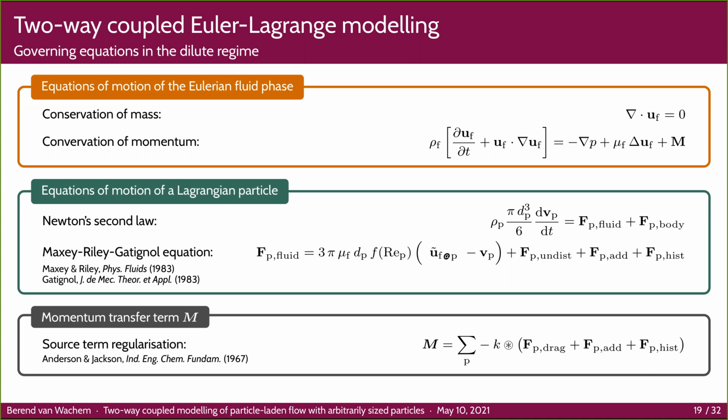Of course, in a fluidized bed, there are lots of things going on, and there are lots of approximations made. However, even if you want to get the dynamics and the pressure drop correct, you will need to know quite accurately what the drag force is on the fluid in each cell. So I would say that the errors you make in a standard Euler-Lagrange simulation of a fluidized bed, the ones that I discussed today, are more important than the typical shape or collision forces, even though, of course, they will present an error as well. Okay, so if I would ask a student to focus on the bottleneck in fluidized bed simulation, you would say it's not the shape of the particles, it's not the collisions, but it is the hydrodynamics of a single particle.